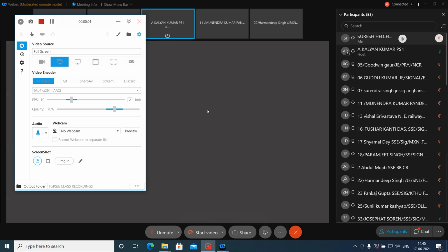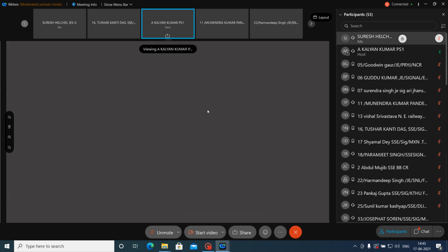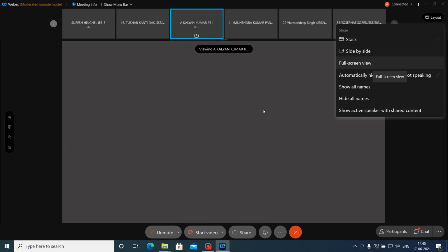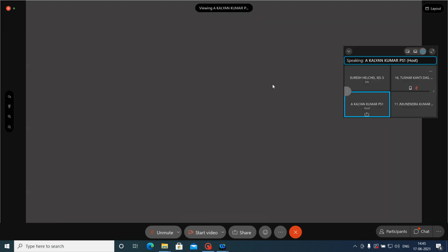Particular sequence. Only after closing the LC gate, we need to clear the signal if it is in the en route path. Like that, between two variables, either the signal, point, track circuit, or all the signaling gates, there is a particular relationship. They need to be operated in a predetermined sequence.